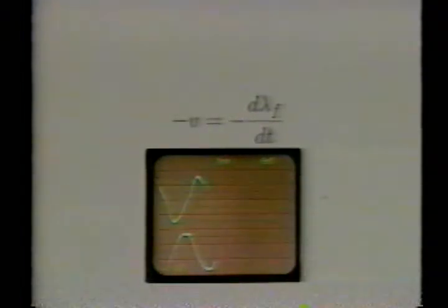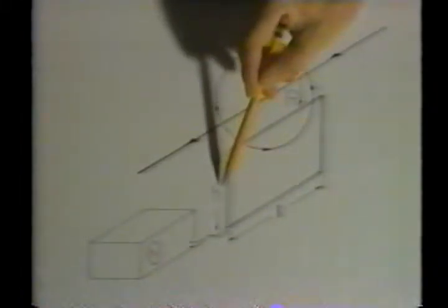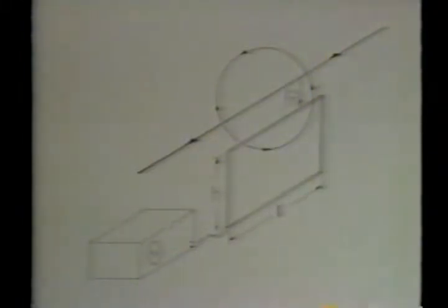The coil height is h, the length is L, and the number of turns is N. In terms of these parameters, this is the flux linkage. The flux linkage for a single turn is the surface integral. The total flux linked is obtained by multiplying by N. R is the distance from the wire to the top of the coil. In the experiment, this distance is R. Faraday's law gives this as the coil voltage.